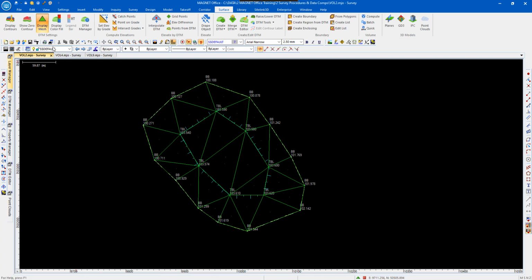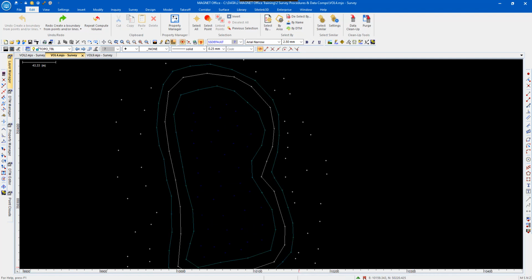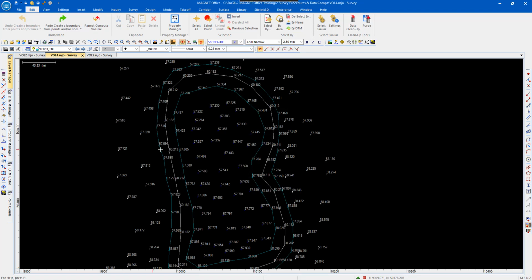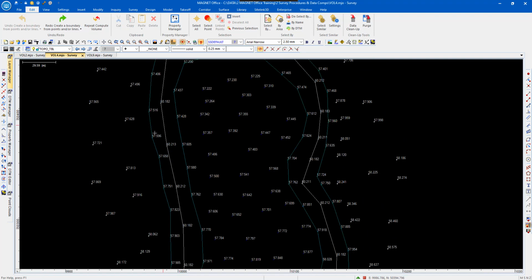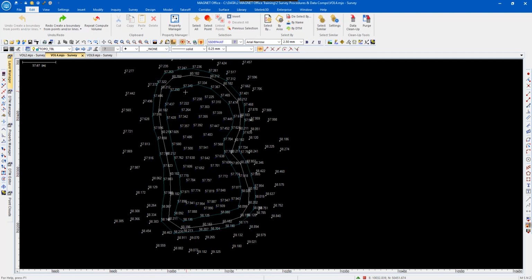Okay, now the second method, we're going to be doing it by slices. In this particular instance, we've got a gully which we're going to be filling up with water. These levels around here, if I turn on my elevations, and the hot button there, the top of this bank is around the 60 meter mark. What we're going to do is fill that up to about 59 meters, up to this middle area there, which is called Topo TBL. That's the name of the actual string or line work that goes around there.